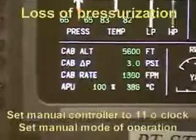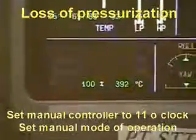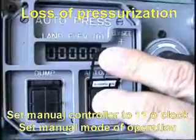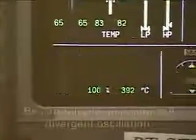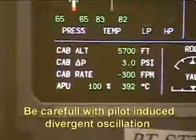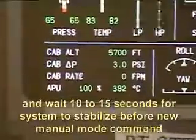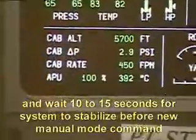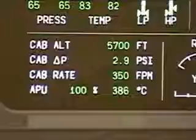In case of rapid loss of pressurization during automatic mode operation, set the manual controller to the 11 o'clock position and immediately set the manual mode of operation. It has been observed that cabin altitude indication may vary under these circumstances. Therefore, it is recommended to wait until the cabin altitude indication stabilizes, and then the manual controller should be operated as required to control cabin altitude. Remember, the manual controller gain is very sensitive, and the response time to the command may take a few seconds.